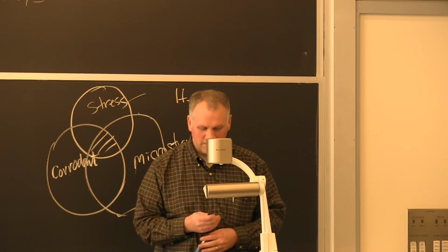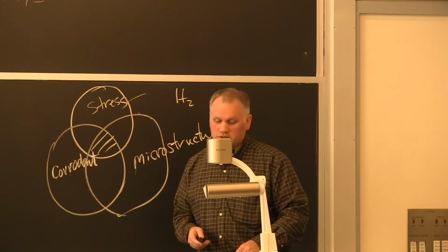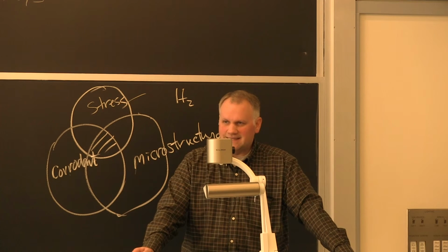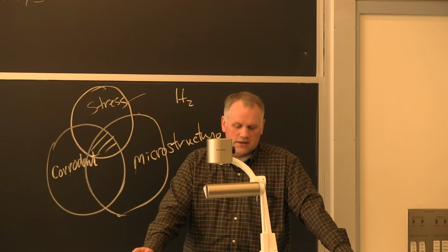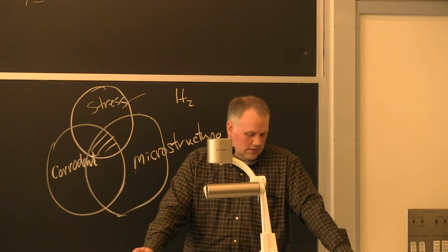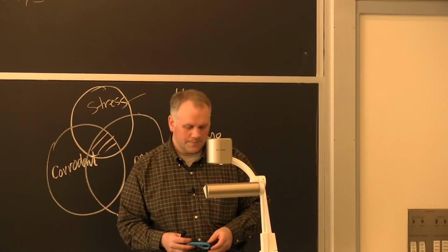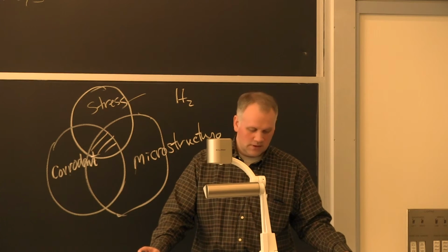So a few ways to prevent strain age cracking. You can select a resistant material. Alloy 718 was developed much for this reason. It's strengthened by the gamma double prime strengthening precipitate rather than the gamma prime. So it's got lower titanium and aluminum.